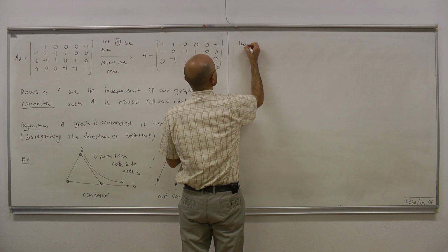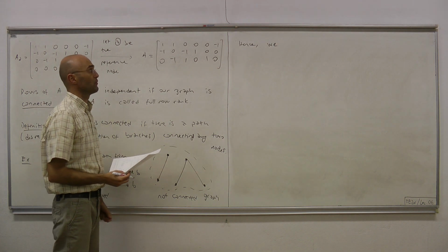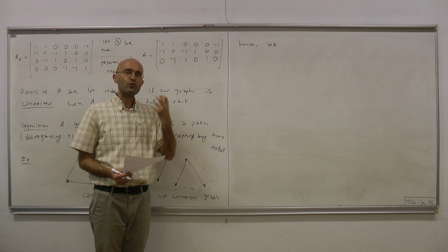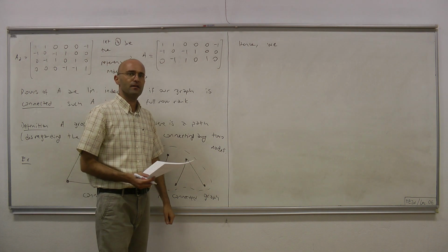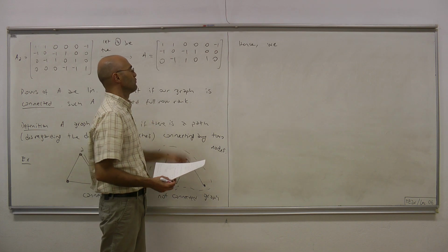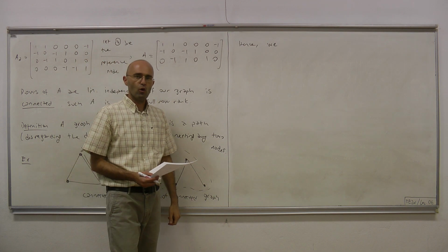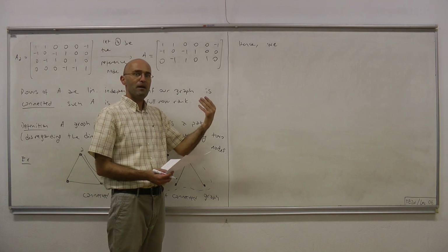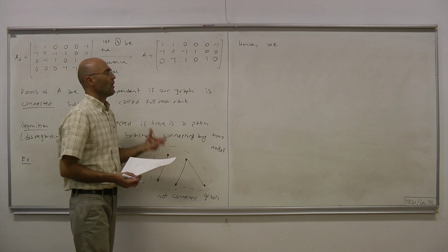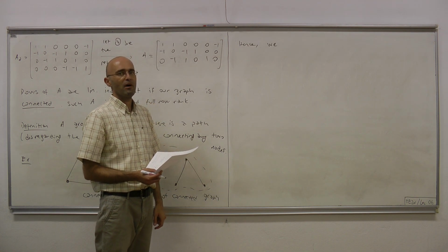Hence, for a connected graph, at least, or for a circuit with a connected graph, to write all the equations coming from KCL in a minimal way, what you do is you construct the reduced incidence matrix, which first you can construct the incidence matrix, and from that just eliminate an arbitrary row, and what remains is the reduced incidence matrix, and that matrix times the current vector equal to 0 contains all the constraints imposed on the circuit currents by KCL.